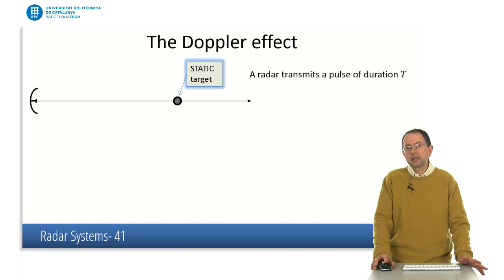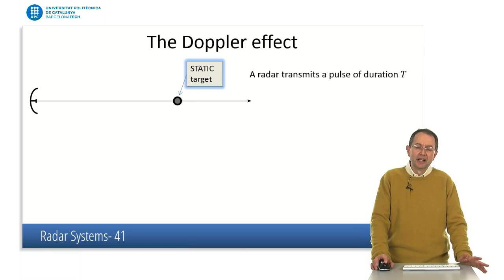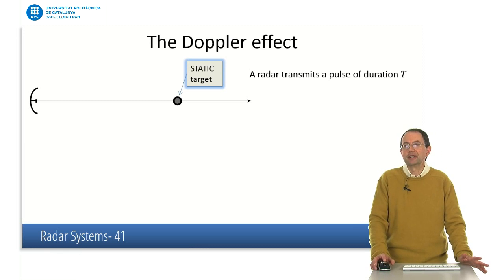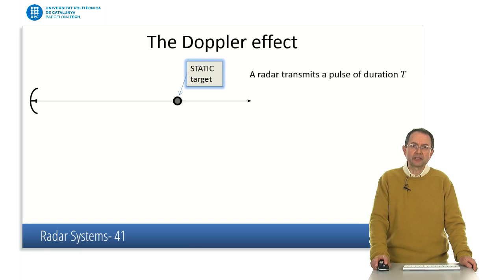So it can be applied to most radars, but actually what happens is that the radial velocity between target and the radar induces a time dilation phenomenon, or change, in the echo signals, which can be interpreted in terms of a frequency shift, but actually it is a time dilation process. So to understand this, let's consider now a small animation here.